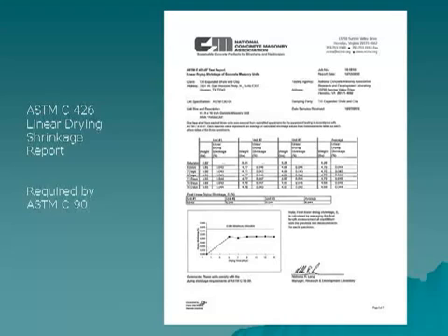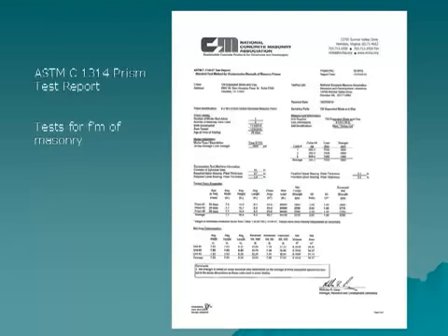But what is the F'(m) of this same block? F'(m) being an indication of the concrete masonry meeting the expected masonry strength for design. For this, we test prisms. ASTM C 1314 is used to construct prisms to confirm the F'(m) of masonry.